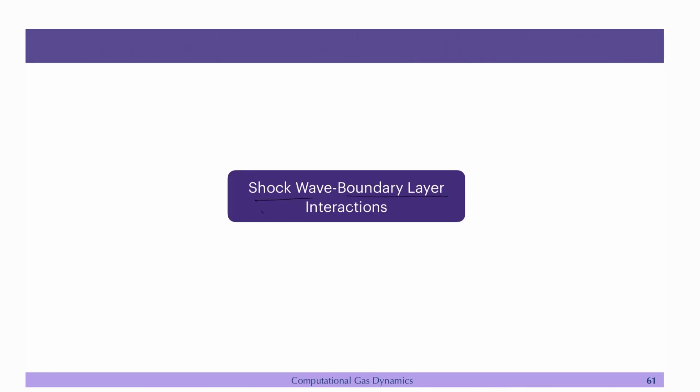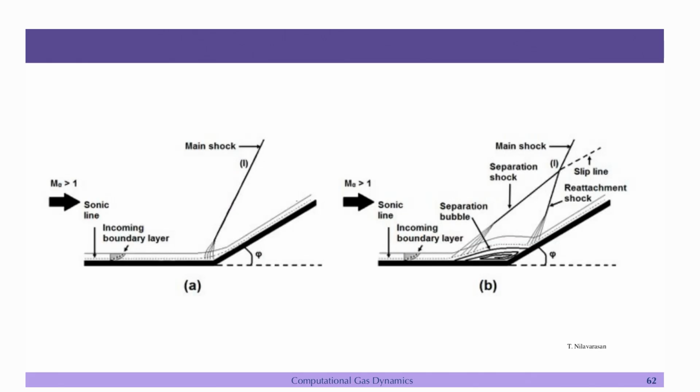Till now what you have seen is that if the equations are Euler, there is no viscosity, the shock wave will come and depending on that it will change the flow. Let me show you an example. If the flow is Euler, and let us say you have this compression corner, you know that depending on the angle you have, you may have an oblique shock or a detached shock, right. You know this theta-beta-M relation.